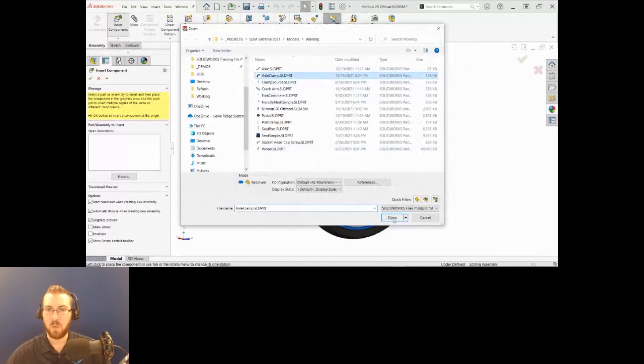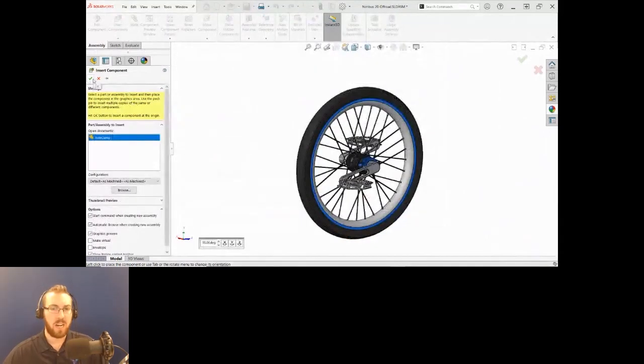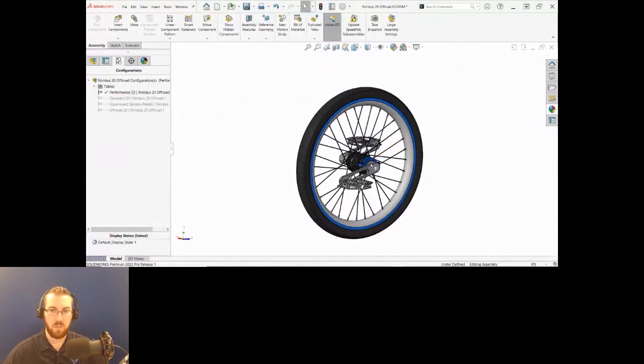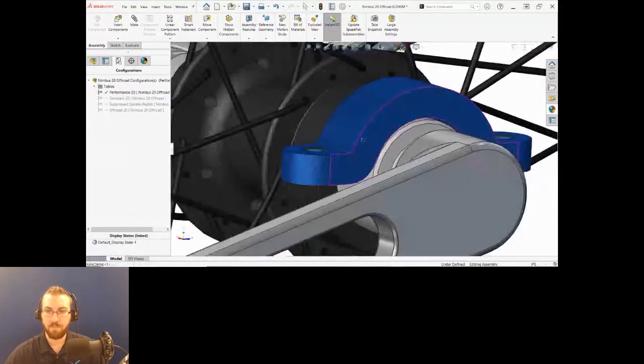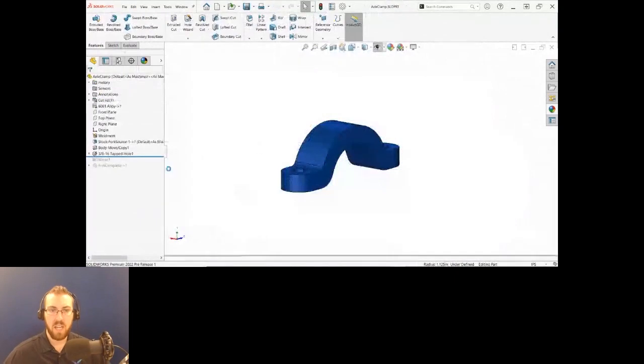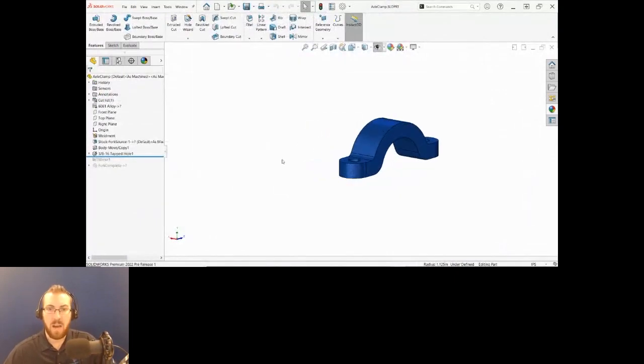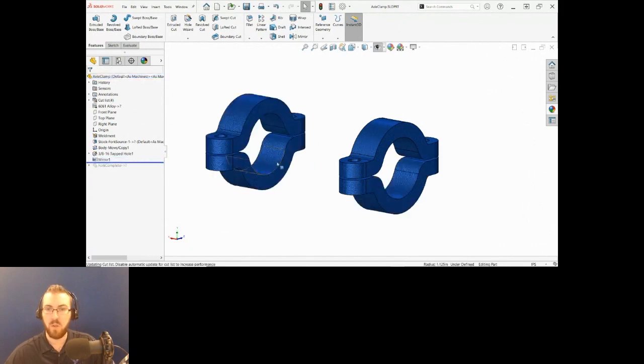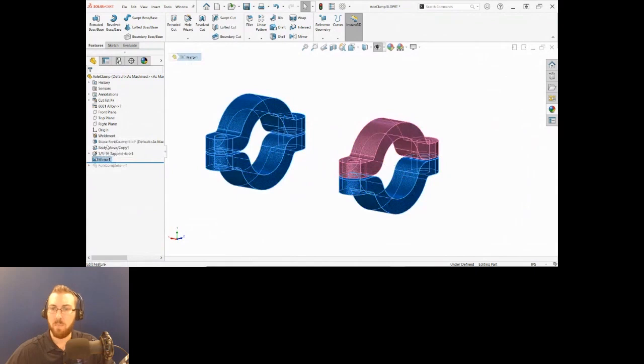So you've got the axle clamp set up. I'm just going to use the check mark for this because I positioned it so that it would be fixed in the proper position, like so. And when I open this up, you'll find that it's rolled back. Now, rolling forward, watch what happens. This is one single mirror feature right here. And rolling forward, it results in 3 additional instances of the axle clamp body. This is really simple to use.